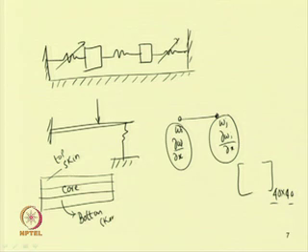In this case, one can take the classical theory. If one takes the classical theory, then one can write the displacement of top, bottom and core to be the same in the transverse direction at a particular section. Or if one takes the higher order theory with a flexible core, then the transverse displacement of the top and bottom layers will be different.